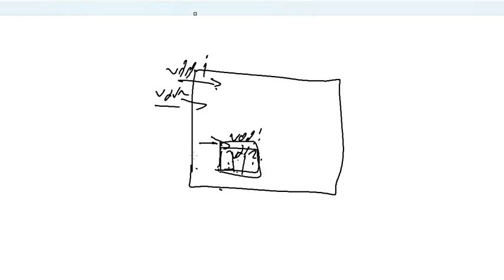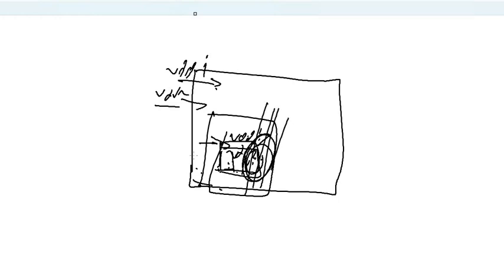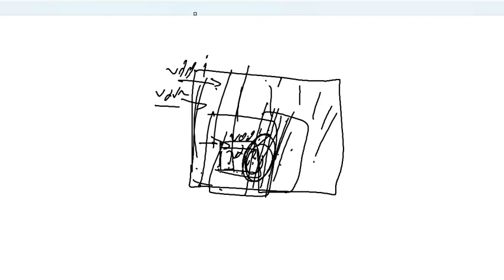First thing, you have to always check whether my module is working on one power supply or more than one power supply. And you also need to check at the next level of the module, if I keep my modules on this side, how are you planning the power mesh at the top level? So, at the top level, the guy might have planned the power mesh wherein VDD2 is used only in this section, and the rest of all is VDD1 over here. And only this guy here is VDD2.